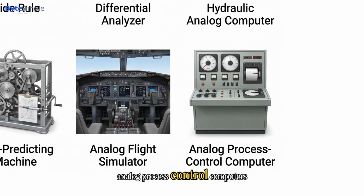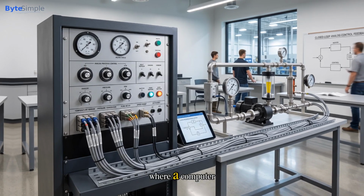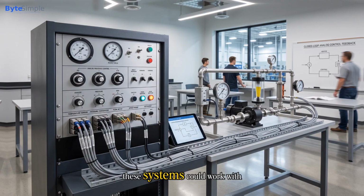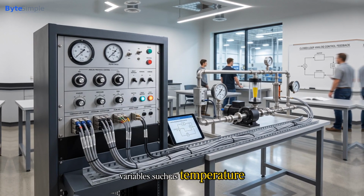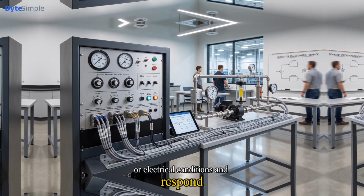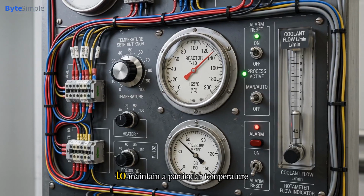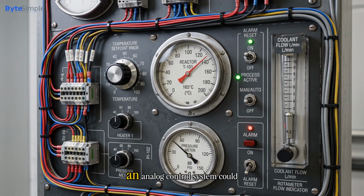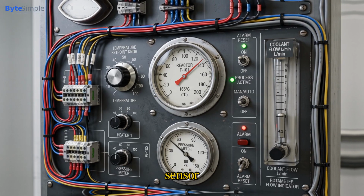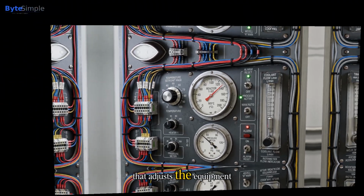Analog process control computers. Analog computers were also used for process control, where a computer continuously monitors and influences a physical system. These systems could work with variables such as temperature, pressure, flow, speed, or electrical conditions, and respond as those values changed. For example, an industrial process might need to maintain a particular temperature. An analog control system could receive a continuously changing signal from a sensor, compare it with the desired condition, and produce a control signal that adjusts the equipment.